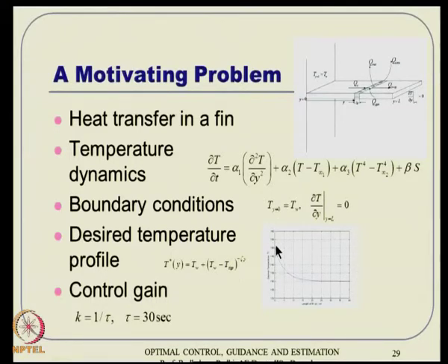because it is kind of unnatural to assume that it will be the same throughout the spatial domain. We can do that with heavy emphasis on control, but practically it may not be a good idea, and may not be that easy to do. So we assume something like this, which is very much reasonable. The wall temperature is something like 150 degrees centigrade, and slowly it will come to something like 130 degrees along the spatial domain. Twenty centimeters away it is 130.